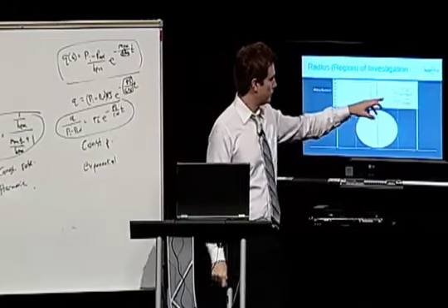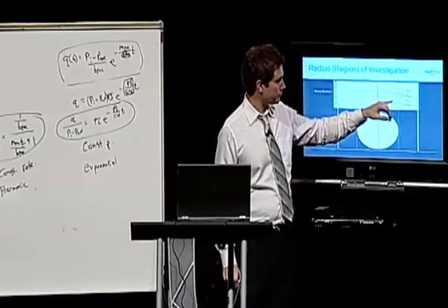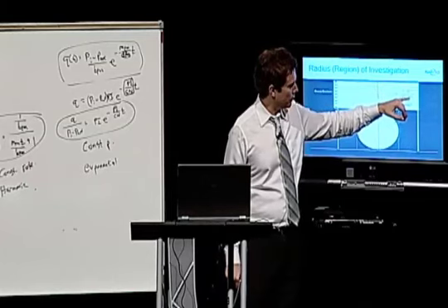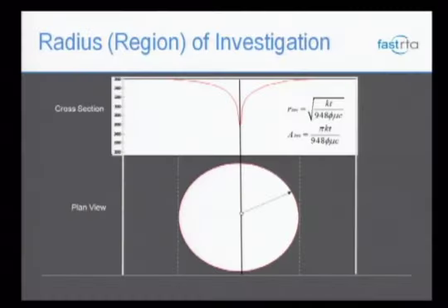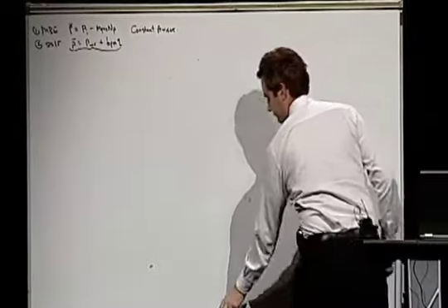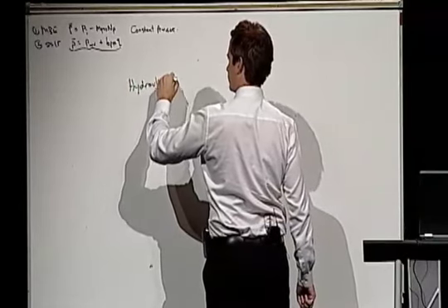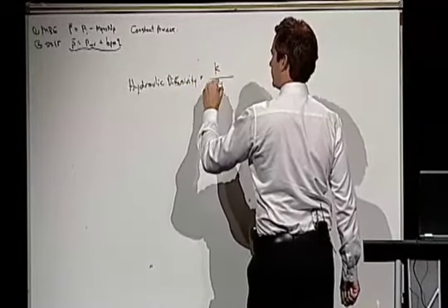So what I want to draw your attention to here is this equation, and it's a fairly simple equation. Really the only variables that are in here are time and this combination of permeability, porosity, viscosity, and compressibility. And this conglomeration of variables is called the hydraulic diffusivity. So hydraulic diffusivity is equal to permeability divided by phi mu c.